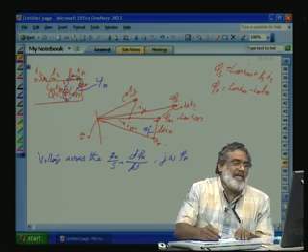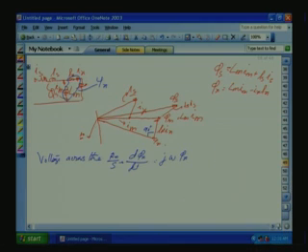If you look at the IS, previously with respect to air gap flux, we defined IS as a vector sum of IM plus IR. Also, we can define it with another component, which is, let us say, the magnetizing component, the rotor flux producing component IMR, that is this one, and the perpendicular component, which is also 90 degrees.